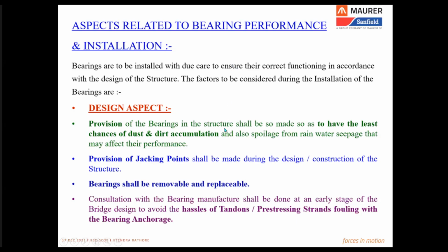So in terms of the installation aspects, we have to make sure, you as a designer, you may be designing the bridges or you may be doing the execution part, maybe now or in future when you will be coming to the profession. It is important for a bridge bearing to ensure that the provision or location of the bearing is such that it has the least chances of dust and dirt accumulation around, and the rainwater shall not be reaching the bearing locations and spoiling the bearing because otherwise it will have corrosion.